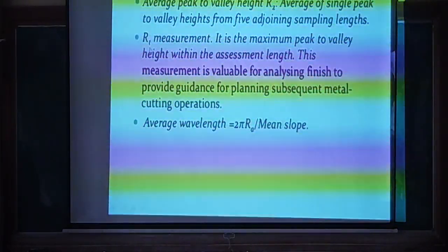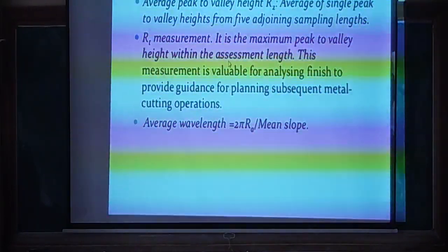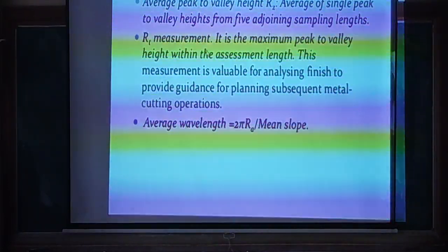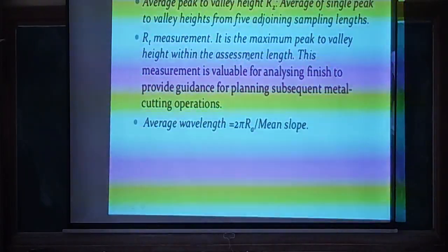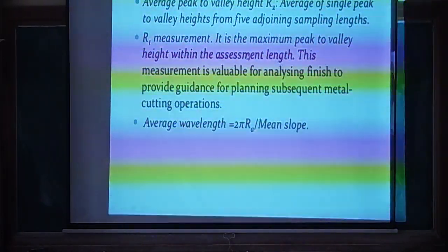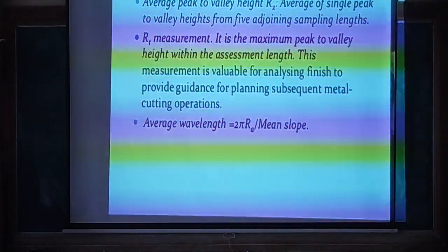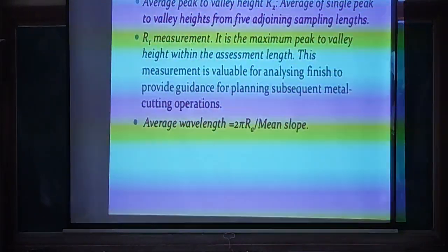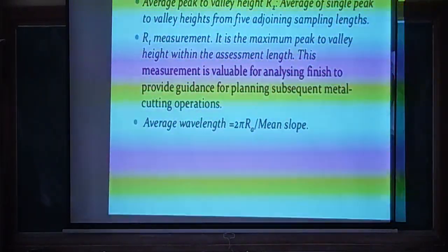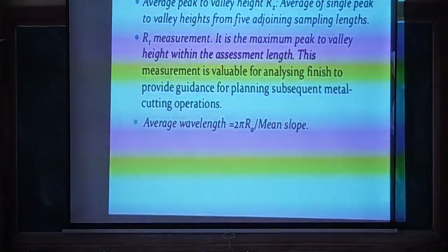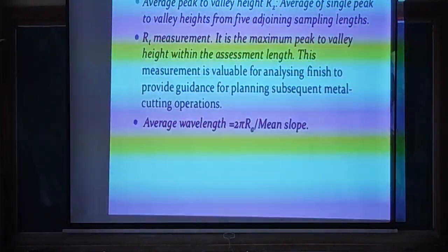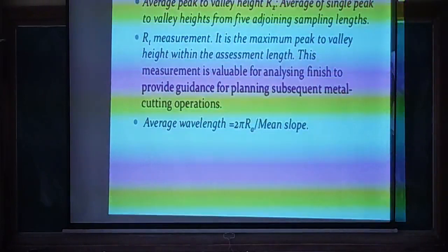So Rt, what is the Rt measurement? It is the maximum peak to valley height within the assessment length, whatever length we want to assess. That is what we call the Rt measurement: the highest peak to valley height within the assessment length.